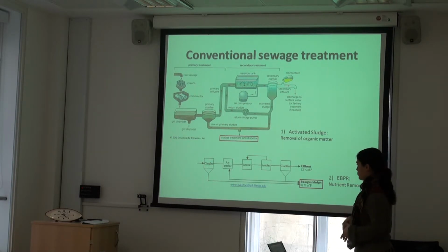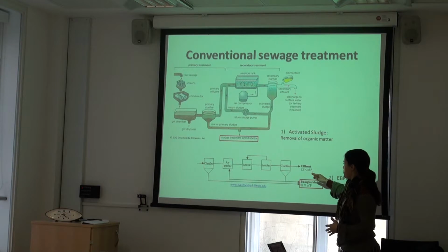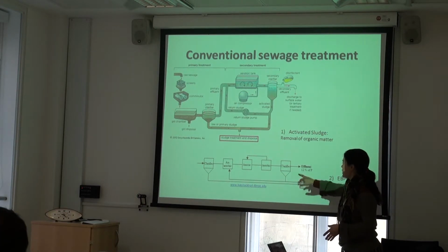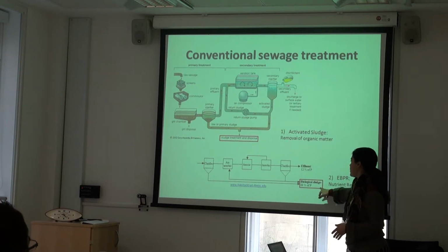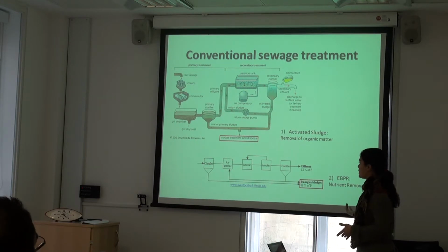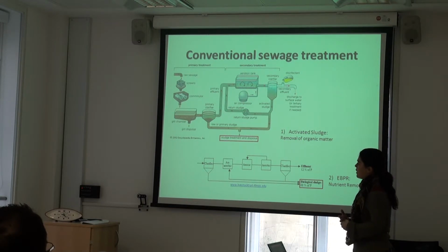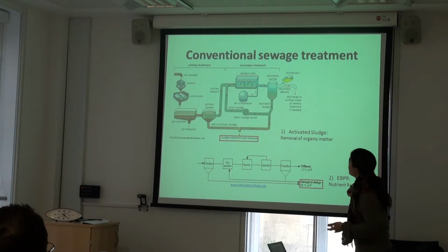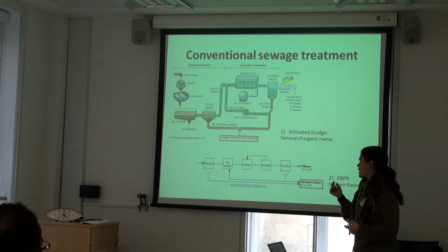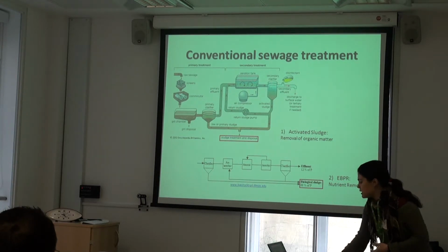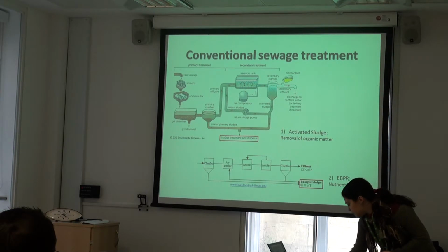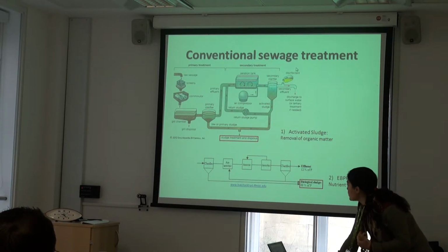Really the phosphorus is not removed, it's actually all concentrated in the sludge. It's taken out from the water, 12%, but it's only in the sludge, so really it's still there. And there is some elimination of nitrogen, because the nitrogen is first converted from ammonia, from the input, to nitrate, and then from nitrate to nitrogen gas. Although it's also accumulated in the sludge, so the sludge needs further treatment because it's where everything is concentrated.